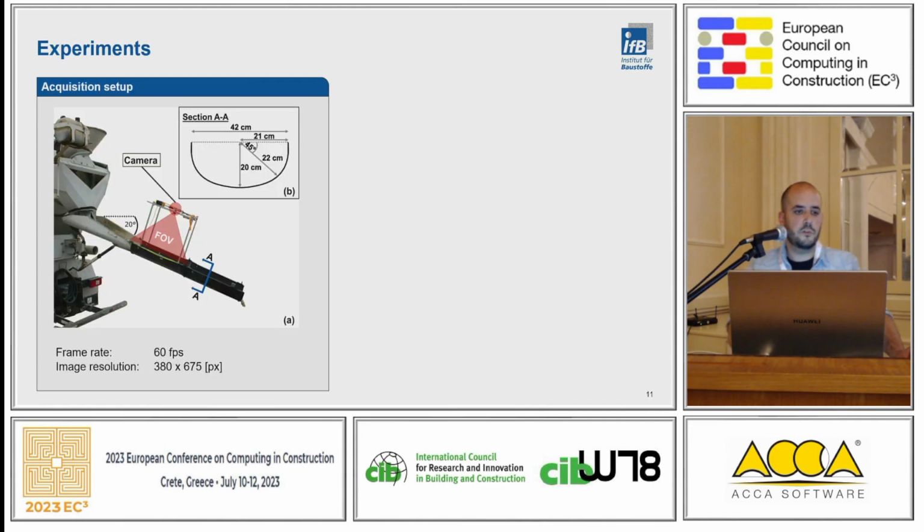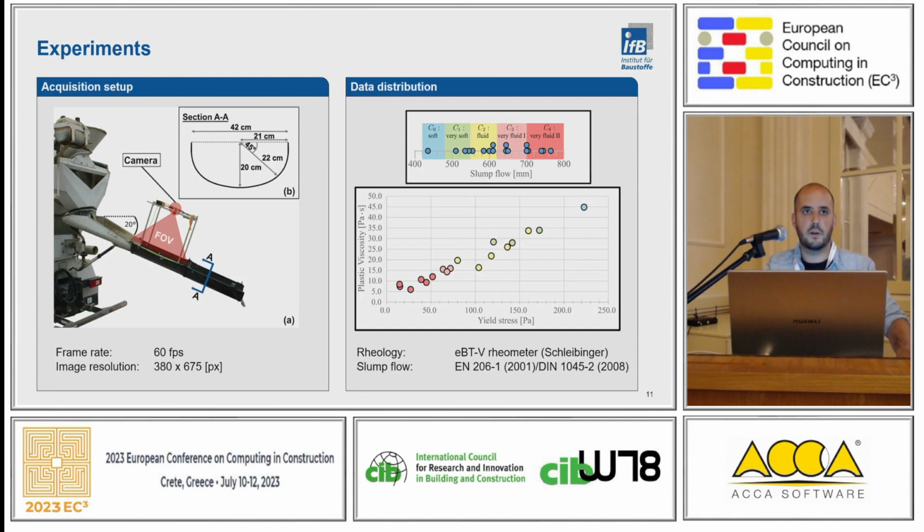To test this approach, we went to the construction site and built a real channel equipped with a sensor, the channel with a fixed size and a fixed slope to have constant boundary conditions. And we acquired quite a huge data set comprising several concretes with different reference values. We used the slump flow table test and the concrete rheometer to acquire reference values. And as we can see here, we have a broad coverage of the concretes with the target parameters.